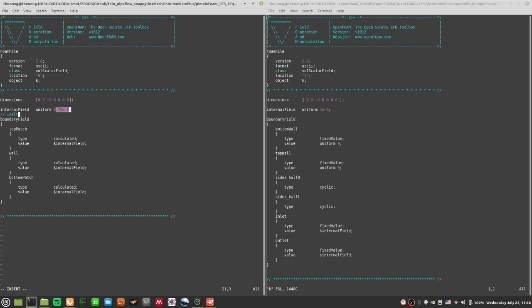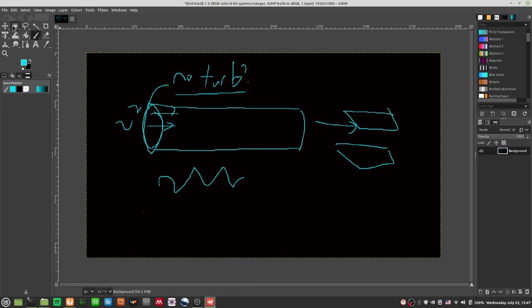Inlet k, kinetic energy for the LES k boundary condition can be 0.2 times the inlet k for RANS. So what am I saying here? What's the rationale here?